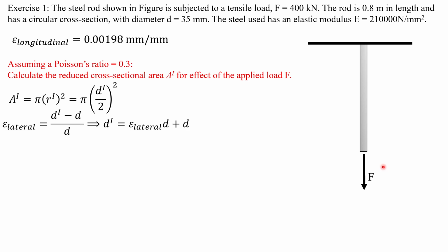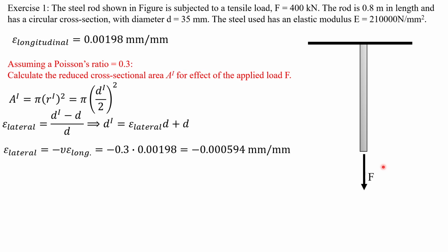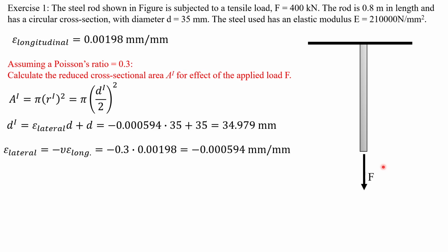And then from that, what I don't have is the lateral strain. I know Poisson's ratio has lateral in it. There's the equation there. I pull it out: strain lateral equals minus Poisson's ratio times strain longitudinal. And now I have everything that I need. From before, I've got everything else. I can then just start populating it, getting my answers.